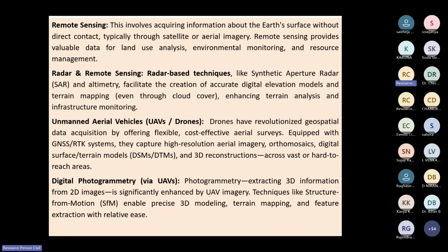The radar images are continuous, whereas if you consider digital photogrammetry, it is event based. Suppose one region is there, you can capture that entire region and then with the help of GIS software, you can map it and prepare the region maps. But you cannot get the spatial and temporal data again; you have to capture it with the help of devices. Whereas remote sensing is a continuous process. Images are acquired continuously, we analyze them, and we use them for our application purpose.